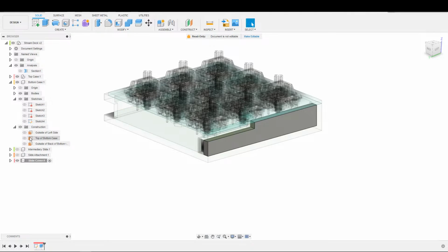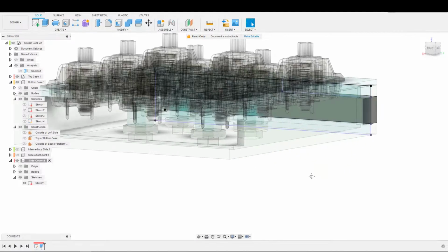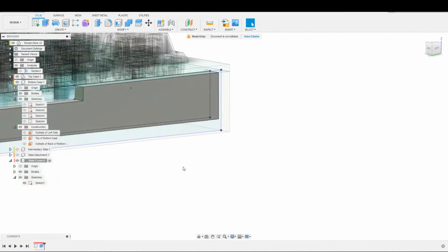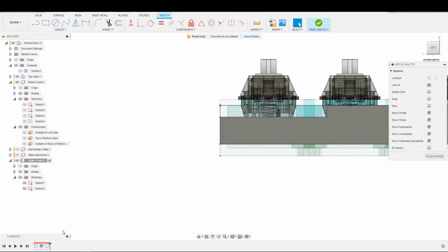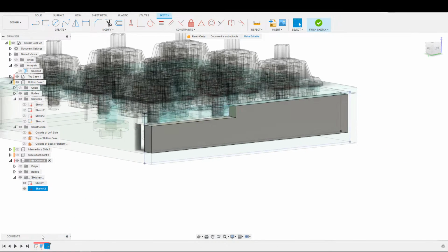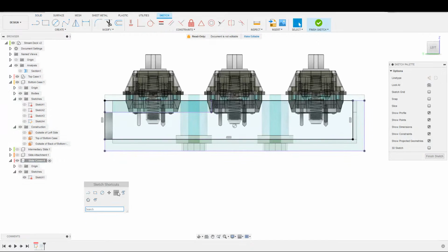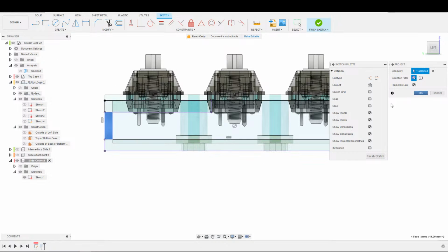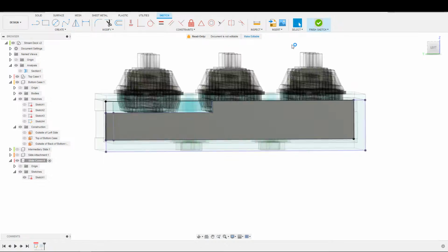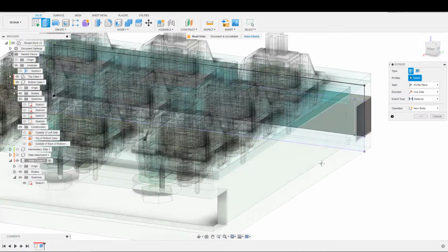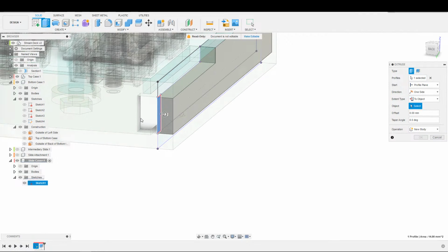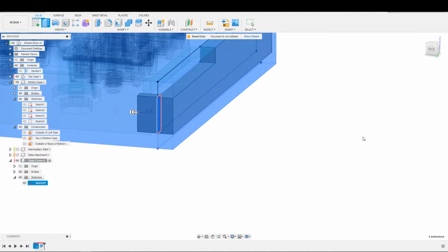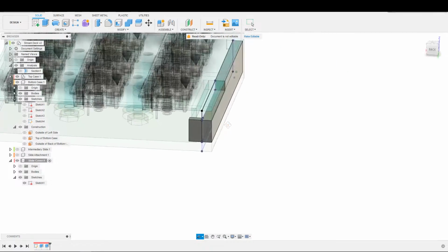So let us open that sketch back up. Do I have that projection there? It doesn't look like I do, so I'm going to go ahead and project that out now. Whoops. Control Z. Come back into the sketch, project that piece out right there. And then what I wanted to do was extrude that out as well, because again, we're trying to keep this covered up. So distance to object there. I think that was right. The selection looked a little funny.